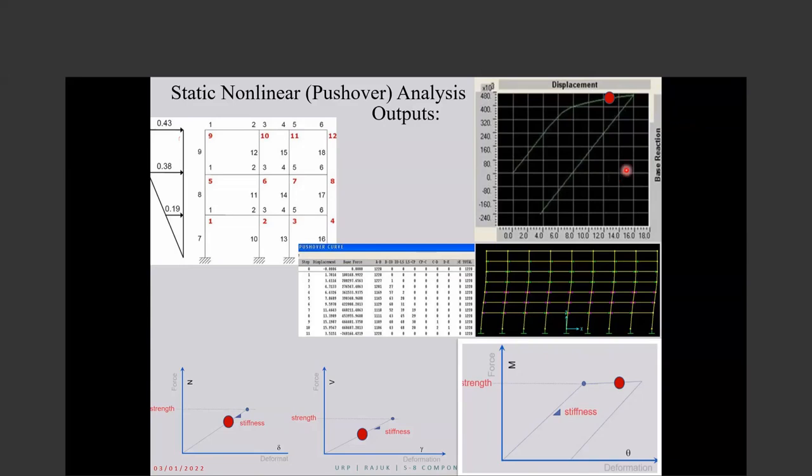We say, okay, let's try another earthquake. So this building, it seems, can't withstand, for example, the earthquake with 2% possibility in 50 years. Try it with 10% in 50 years, the ordinary design level earthquake. For that, this building is around 13 centimeters. So the software begins to push the building.